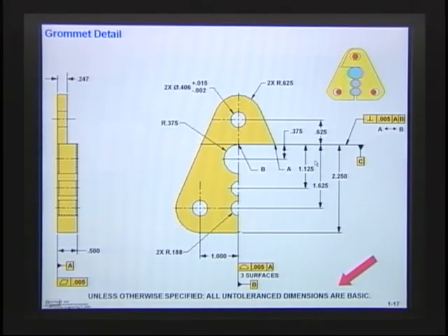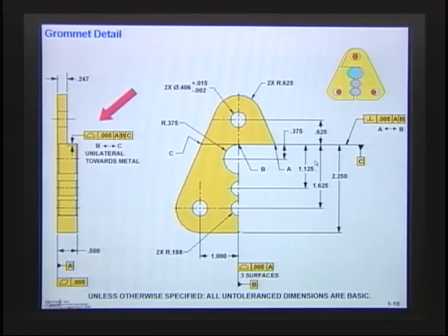All right, the next thing is we have to apply the tolerances. So the first thing what I did is I came in, and I'm going to go after the most important things first. So do you notice that this surface, when the 2 parts came together, that surface there, that couldn't be exactly in line with this feature, because if it was exactly in line, we wouldn't be able to get in. So this part has to be on that line, or it has to be down, right?